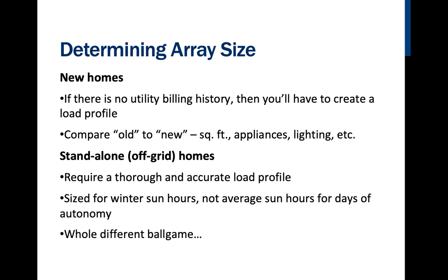Then we're going to size an array to meet the needs of that battery pack. And so the PV array is going to be grossly oversized because it's sized for its greatest need and the lowest amount of resources. That's going to typically be maybe November, December, January, that time period. And it's just going to be grossly oversized. In the summertime, it's just going to sit there waiting to do something.